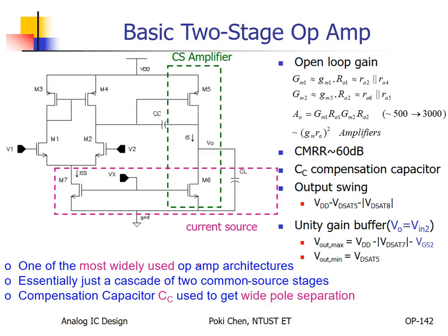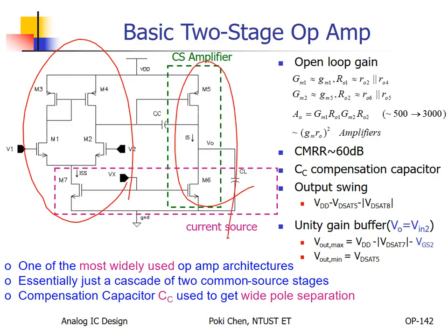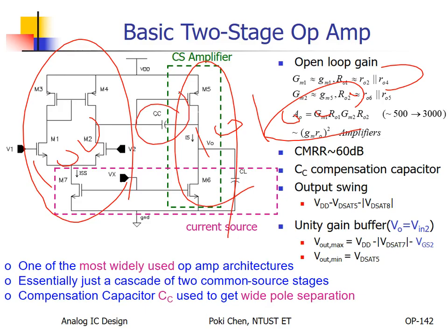You learned it already from microelectronics, so I wouldn't like to waste your time. I only have a very brief introduction. The first stage is a differential amplifier. The second stage is what? Common source. That's it. Okay, but usually it's maybe 100 here and 10 there, so totally 1,000. More likely it will become unstable. So we need compensation. Okay, that's it. And how? Oh, don't ask me because you learned already from microelectronics. Just read by yourself. All right.